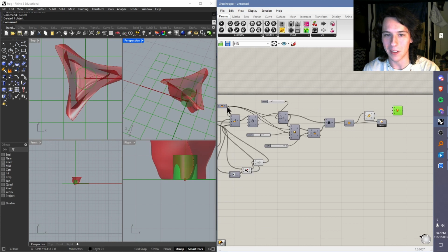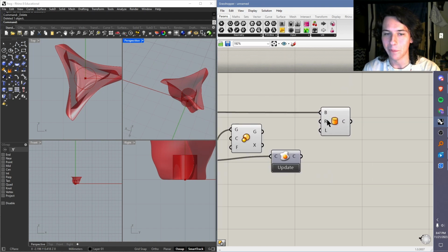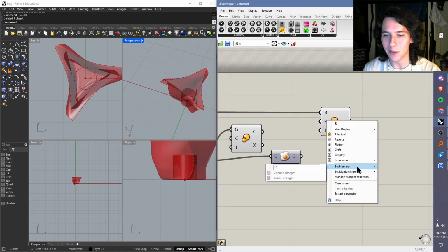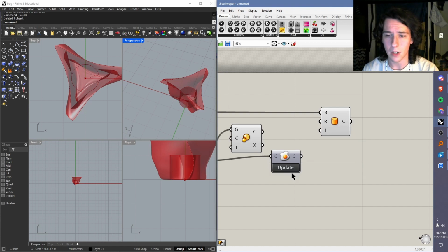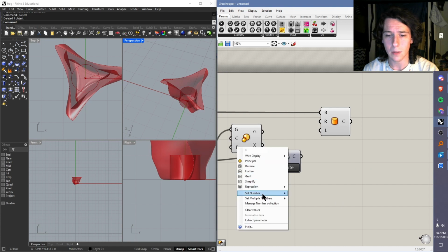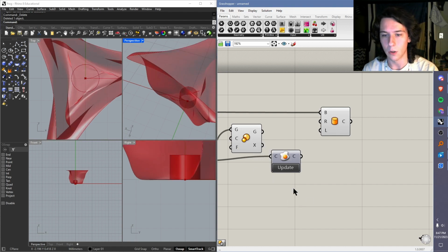The red plane is back. Get rid of it. In this case, B is base plane. I think a pretty standard size for these is like 1.5 inches. So I guess that makes our radius 0.625. Is that right? 5/8. Not 1.5 inches, 1.25 inches. You just gotta trust me when I say that. So let's make this much larger. Maybe not much larger. Let's set it to 4. Sure. Okay, cool.